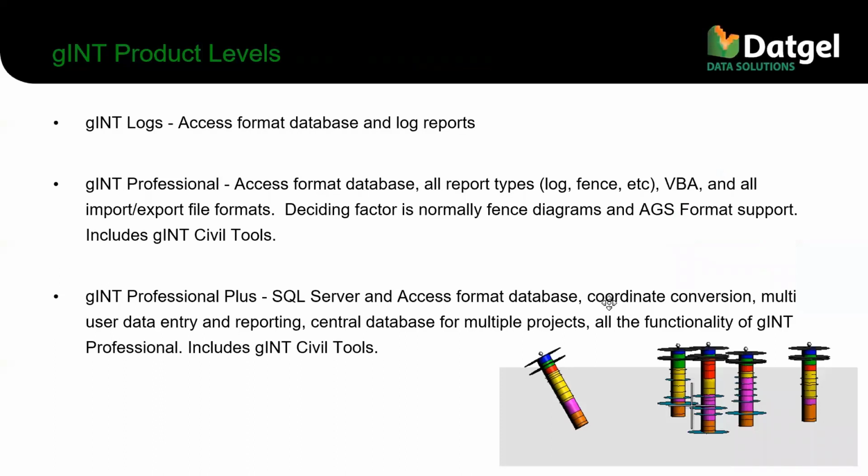GINT has 3 product levels. The CPT tool will work with all of them. However, GINT Logs is a bit restrictive because you can only print a log report. So you can't produce a graph of a dissipation test or a cross-section fence report. GINT Professional or GINT Professional Plus are the 2 products we recommend people buy to use the CPT tool because it has all the reporting options, and GINT Pro Plus is the option that has SQL Server backend support.